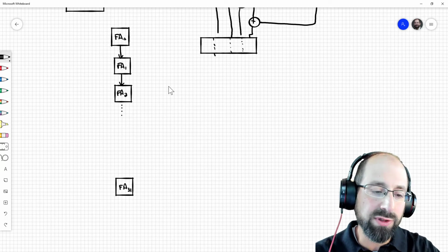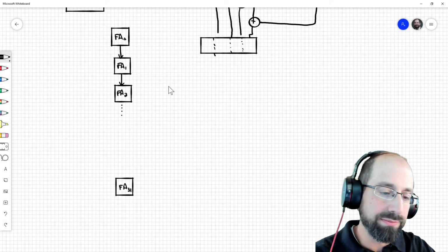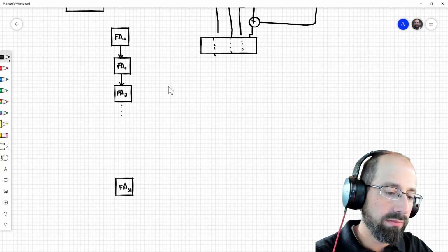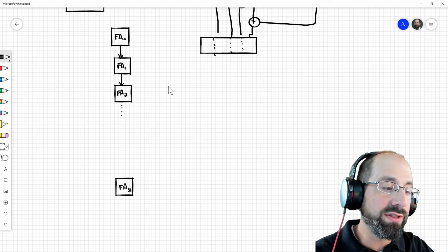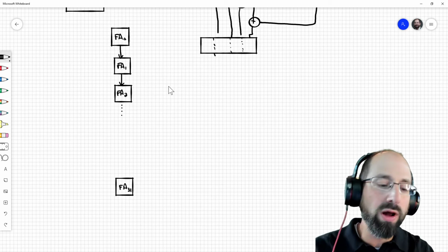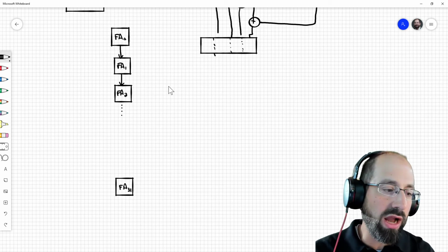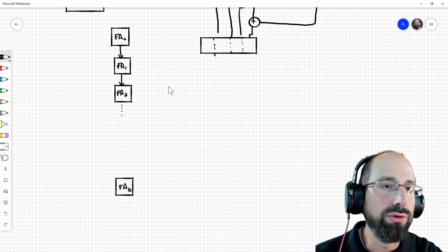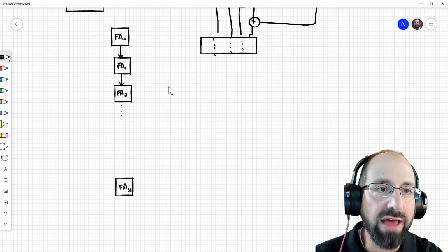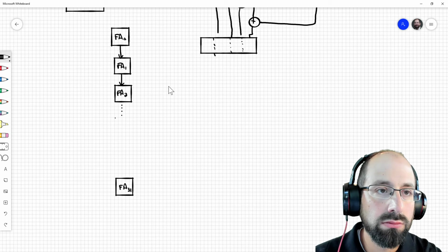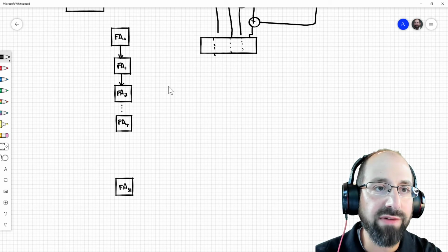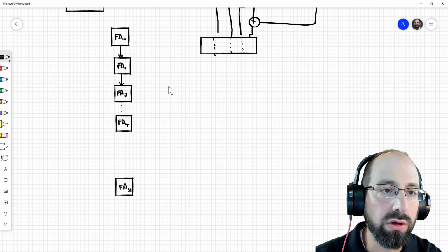If we think of it from the perspective of just this ripple carry adder, the main difference is happening as we go from one byte of our adder to the next byte of our adder. Specifically, if this starts at 0, at FA7 here, and not just at FA7, but also then at FA15 and FA24.